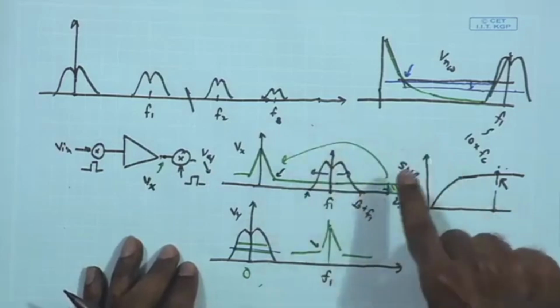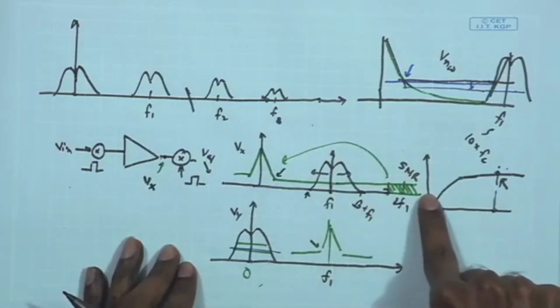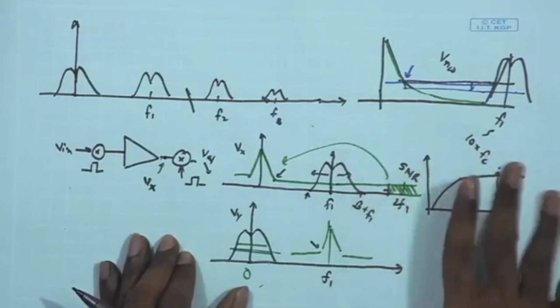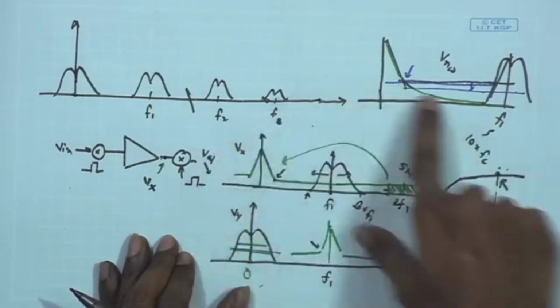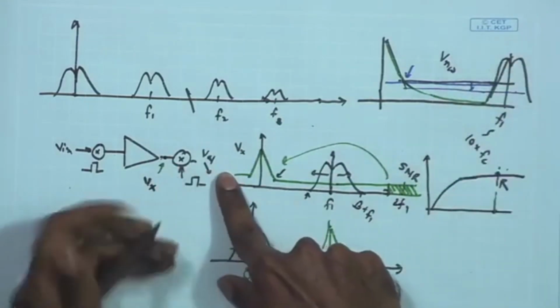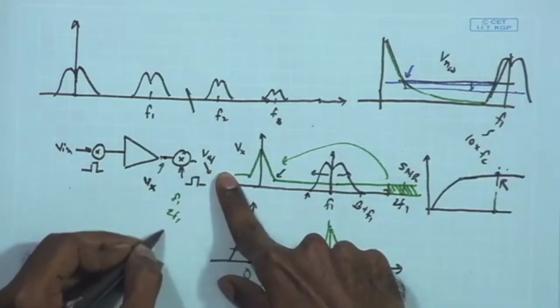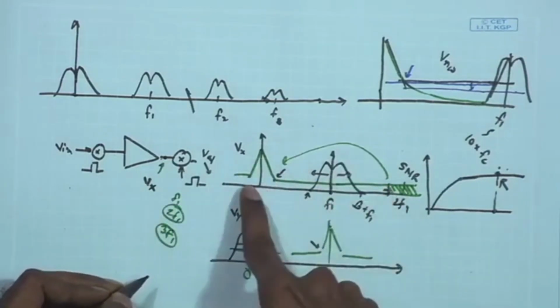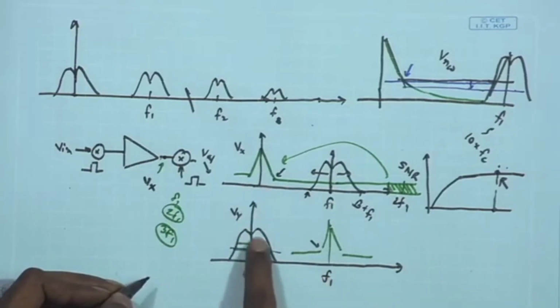In general, if you are having an overall low pass filtering operation, so that after a certain point the noise contributions are getting diminished. So, in that case the higher harmonics of these clock signals, which are anyway diminishing in amplitude. So, you have f1, 2 f1, 3 f1. These are the guys which are bringing my white noise back to the low frequency and superimposing on the DC.